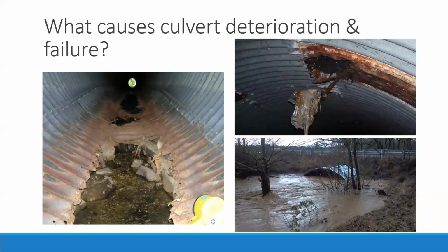So what causes culvert deterioration and failure? Well, one of the most common problems with culverts is deterioration of the invert, usually due to a combination of corrosion and abrasion. Continuation of this, if unchecked, will lead to loss of the invert and the creation of voids under and around the culvert. Since flexible culverts require interaction with soil for stability, loss of the invert may result in severe distortion or collapse of the structure. Additionally, rainfall, flooding patterns, snow melt, and other stormwater events can expedite culvert failure. The water is unable to flow through the structure, and headwater pressure exceeds its design hydraulic parameters.